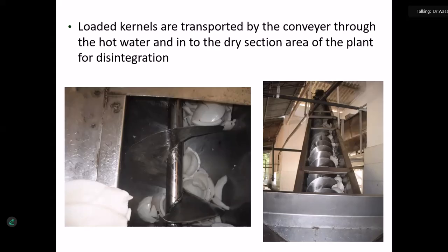The wet section is over. So what are the stages of the wet section? Seasoning is done at home, no? In the factory, seasoning and dehusking are normally on the grower's side. We transport the dehusked nut. So in the factory, what is the first step? The first step is hatcheting, which means removal of the shell. Second step, paring, removal of the testa. Third step, washing, inspection and trimming.